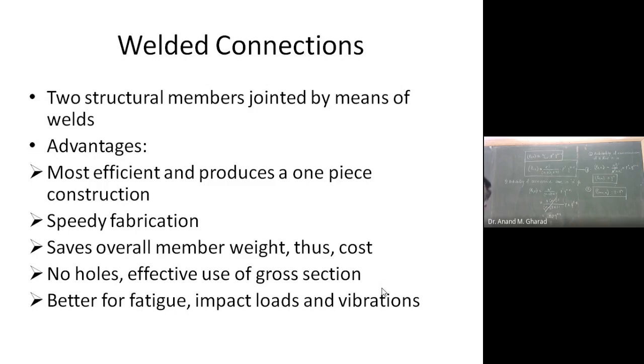If it was a bolted type of connection, definitely we would see the bolts. Here there is nothing like that. Everything is monolithic. Speedy fabrication, saves overall member weight, and thus cost. See, in case of bolted